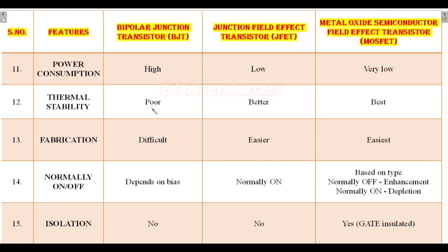Okay, so I have mentioned a formula also regarding collector current, right? So in collector current formula, there will be a leakage current term. So when temperature increases, obviously the leakage current increases. Why temperature increases: normally we can increase temperature or the room temperature may increase, or as a result of high collector current, the temperature may increase. Anyway, as temperature increases, leakage current increases.